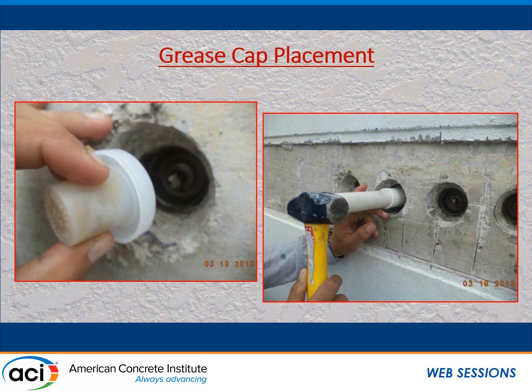Of course, I find it hard to believe that a general contractor or a stressing contractor doing the work initially is going to take this kind of care of setting the caps, but this way we're sure that we've got the cap well seated on a properly prepared anchor and a properly prepared stressing pocket. Because when we do these investigations, sometimes they've even used the wrong size cap, and they fall out. There never seems to be any huge consistency, at least in most of the structures.